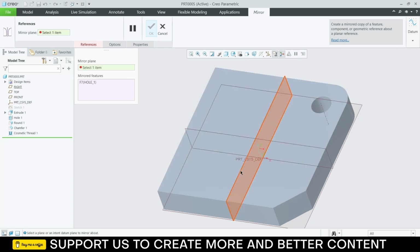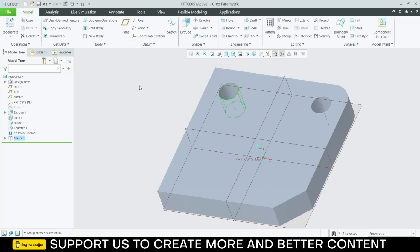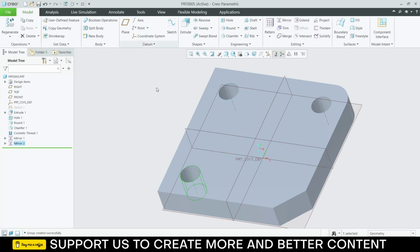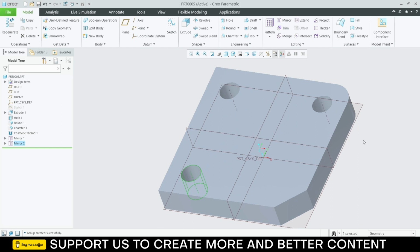So let's say I select this plane. Notice it created. Click OK. Now let's try to do one more time. Click on mirror. I want to mirror about this plane. Click OK. So in that way you can create this mirror command.